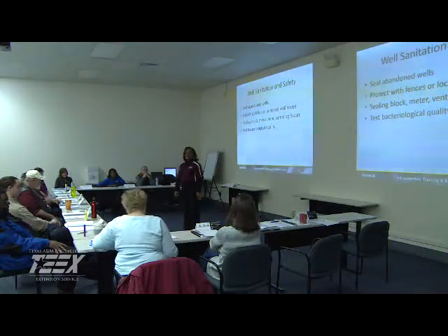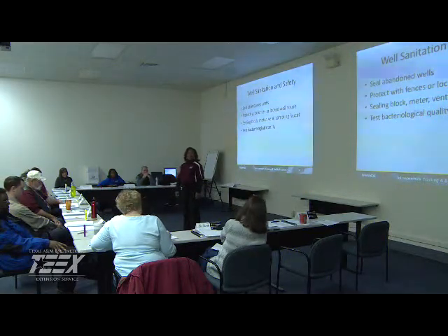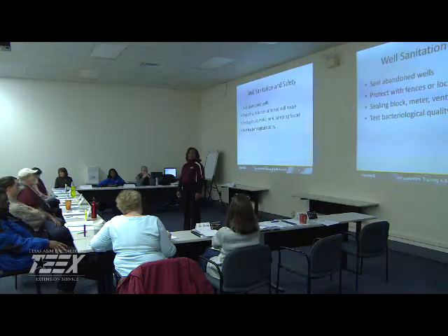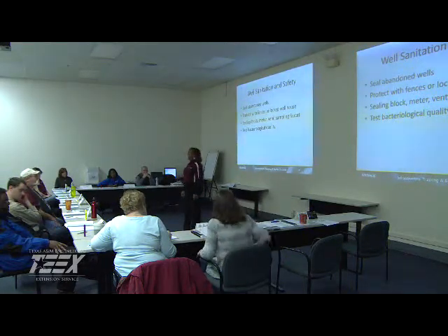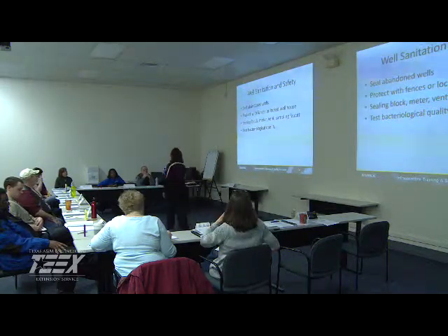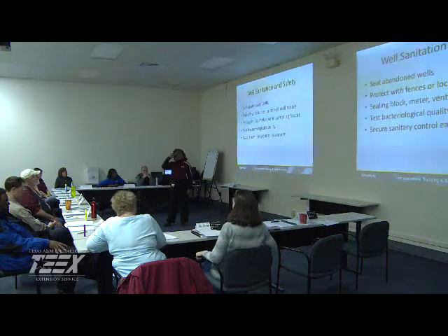It's because you can get a good one right after the chlorine goes out. Over time, the bacteria could grow back, and then we don't realize it. And then the driller says, "Oh, it's not my fault. You got a good test." Oh, no, you've got to pull back tests for 3 days. I like that. But all of our people are in such a hurry.